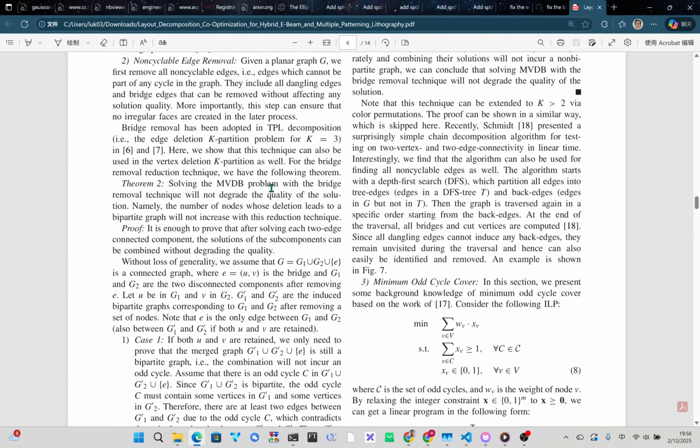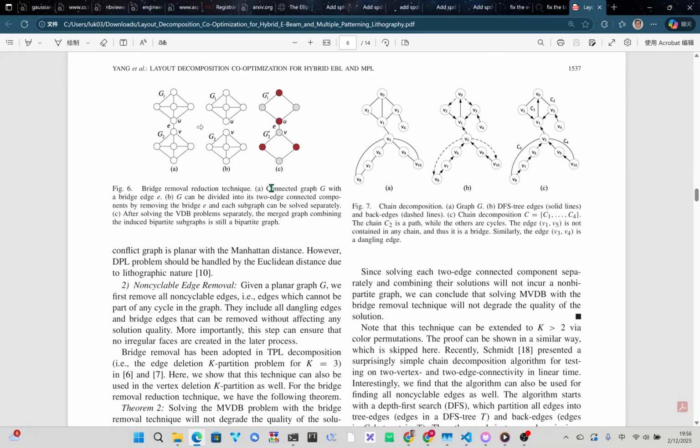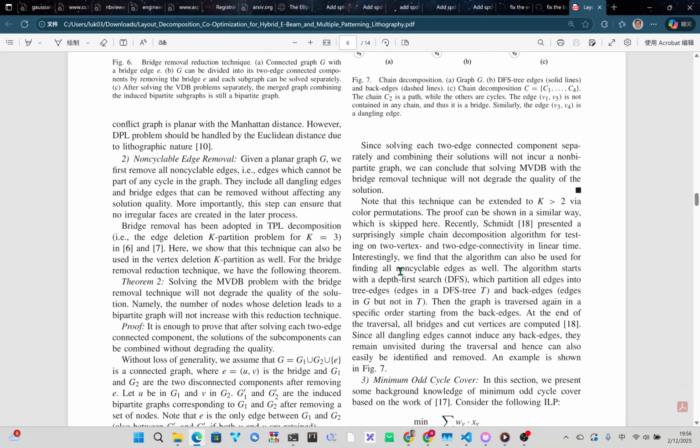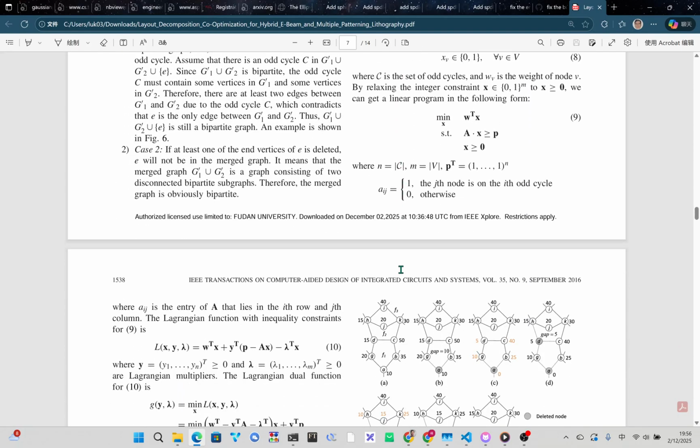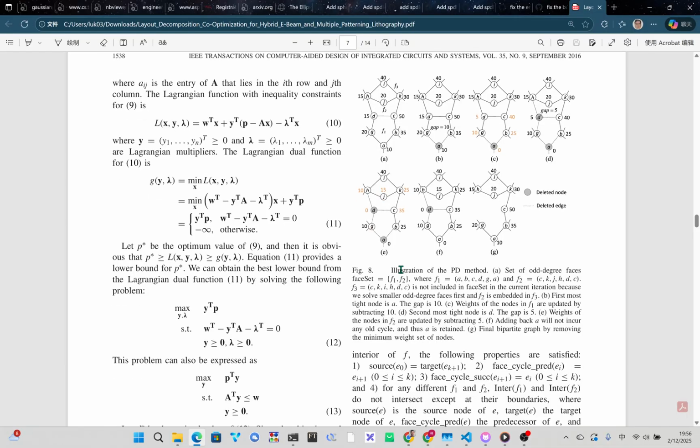This sounds incredibly slow. If you're trying to speed up manufacturing, adding that much mathematical complexity seems, well, counterproductive. It was, which is why the alternative was the non-planar PD method. This one was simpler, more general, and it just skipped that entire planarization process. Instead, it used a rapid depth-first search, or DFS, to find an odd cycle, a conflict.